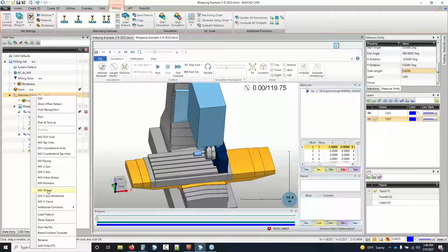But you may be able to use a program like G-Wizard or something that would at least tell you the distance between peaks so you can figure it out. But off the top of my head, making a proper thread, maybe I could get 2 parts to fit together. But no, the thread mill doesn't translate to the 4-axis. It's all going to be single point thread mills from a top view perspective. So inside threads and outside threads.